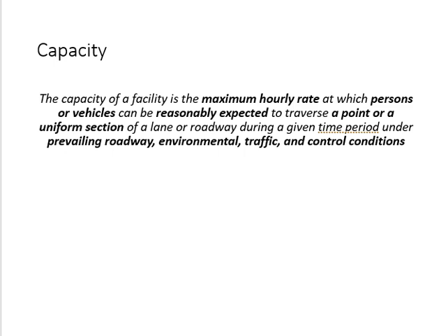10% trucks, 2000. Total is 2000. You have another traffic stream, we have the same number, 2000. But number of trucks are only 2% now. Okay, which one will be faster? 2% or 10%? 2%. 2% will be faster, right? So the capacity in those conditions will become higher.